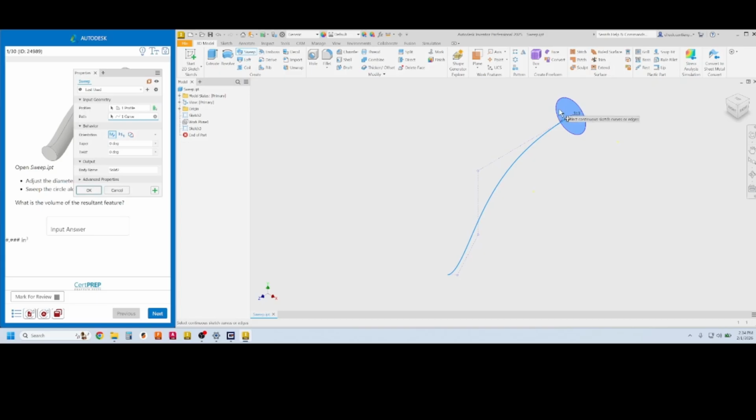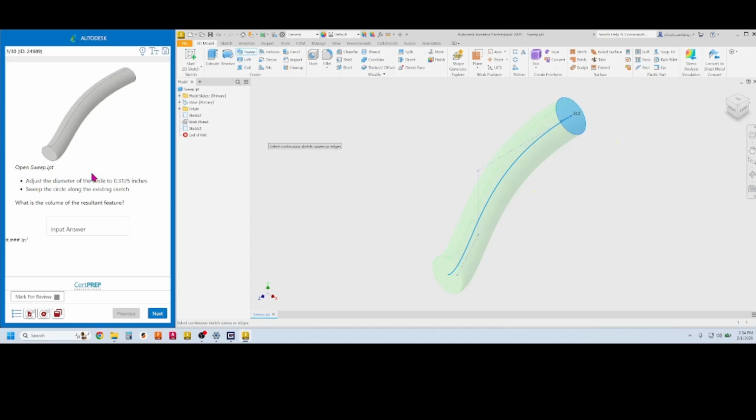It finds the feature. It finds the curve. It does that automatically. But GMetrix in their infinite wisdom, it won't create it like it should. So you have to click this second button to make it extrude. You say, okay. That gives us our solid.